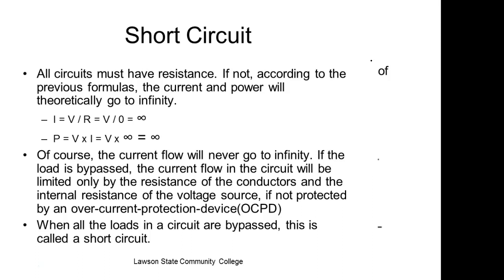So these little batteries I have in my pocket, if I carry a battery in my pocket, the battery's going to give up, right? You understand that? Because of its internal resistance. If you have a regulated power supply, it means if the voltage tries to drop down, it puts more energy into the power supply. But that car battery out there has hundreds of amps available. You get a short circuit on a car battery, guys, you've got problems, because those batteries will blow up on you.